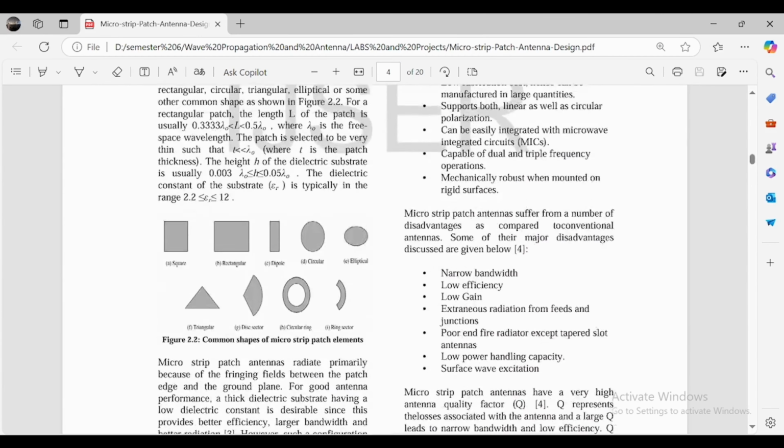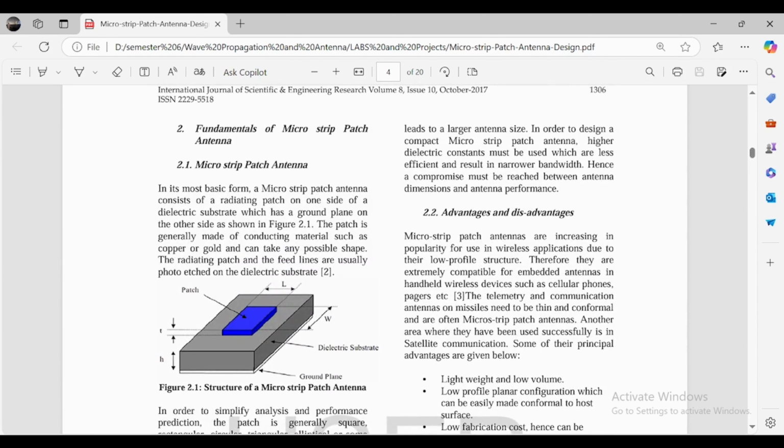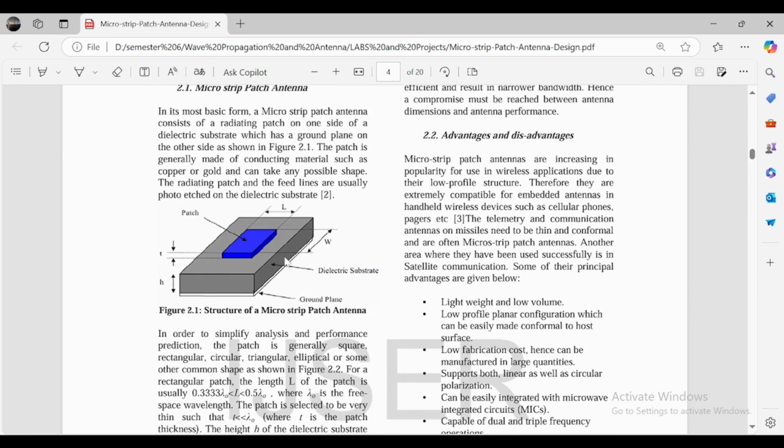So as I said, we must start our journey with one of the papers. Here is a microstrip antenna. You have seen such a diagram that basically describes the patch antenna. It has a dielectric substrate, which is very important while you design an antenna. It is very important to choose a correct dielectric substrate. Below the substrate there is another plate, the ground plate, and there is a small part that is the patch antenna.